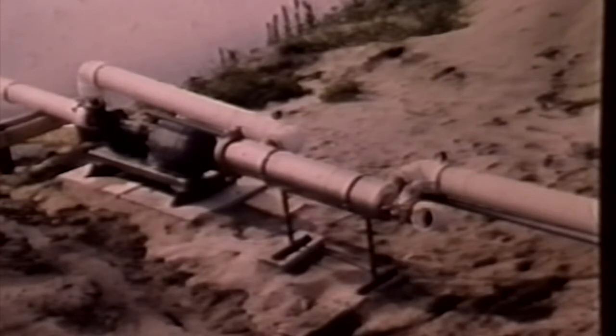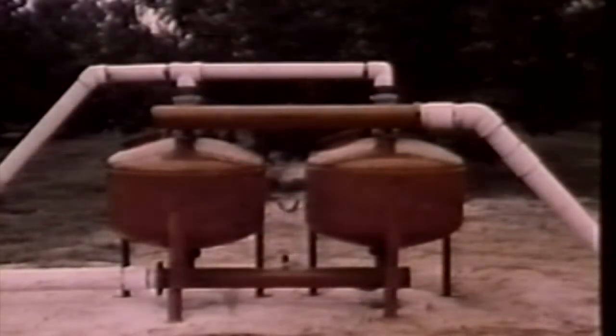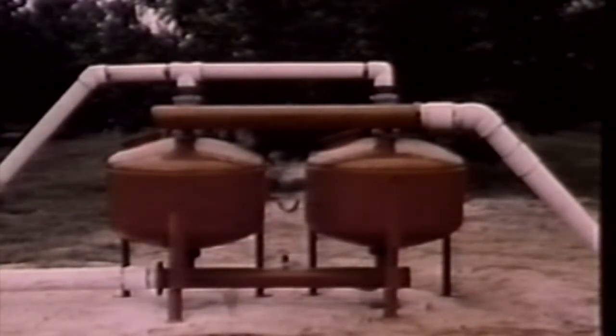The extent of filtration depends upon the type of emitters used and the amount and characteristics of the contaminants present in the water. Several types of filters are used with trickle irrigation systems, such as the screen type and the graded sand type filter. In addition, settling ponds are used to remove heavy loads of sand. Again, the type of filter necessary depends on the trickle system selected and the particulate matter in the water supply. This determination can best be made by professionals who specialize in irrigation systems.